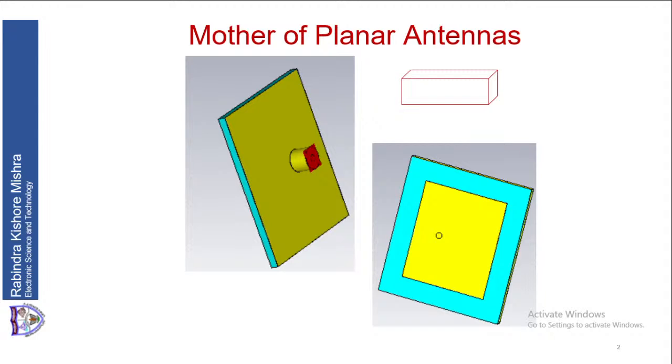So when we design the antenna, our purpose is to ensure that the capacitance is as low as possible, so that energy stored will be minimum and energy radiated will be maximum. So maximizing the radiation will be done by minimizing the capacitance. Therefore, we should have as small an epsilon r as possible. By taking a small epsilon r, we can have a small capacitance, so good radiation, or by having a large separation, large D, or sometimes we call it H. So with large H, we can have small capacitance, and therefore it will radiate.